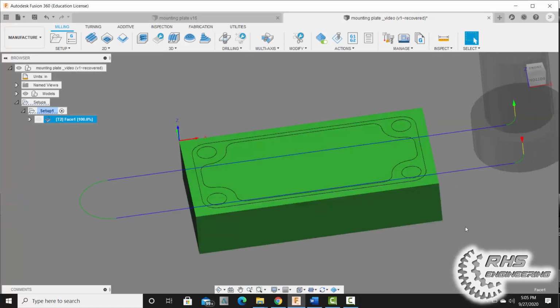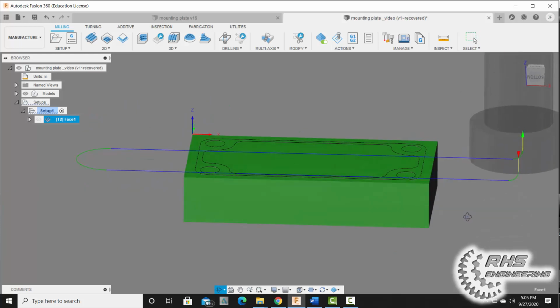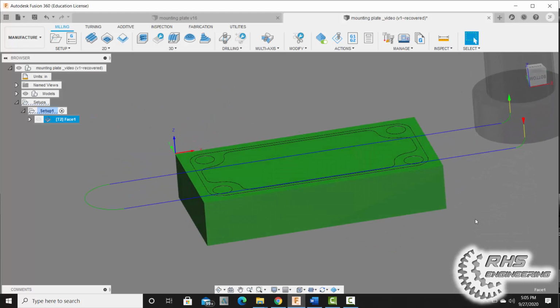And if you notice, here is our tool path. Okay. Now remember, we set our part 0.02 inches from the surface. So it's taking off 0.02 inches off the top, okay? All right, so now let's go ahead and simulate this. I'm not going to simulate every toolpath operation, but to get us started, I do want to simulate this one.